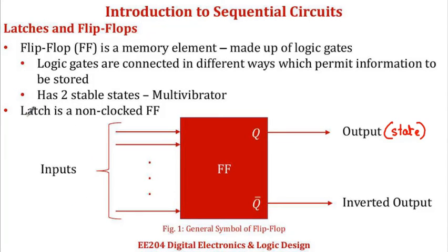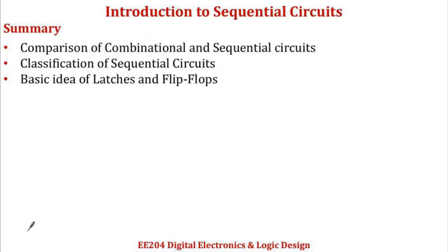Now the term latch is used for certain flip-flops. It refers to non-clock flip-flops because these flip-flops latch on to a 1 or a 0 immediately upon receiving the input pulse, whereas in the case of a flip-flop, you will need a clock signal for the inputs to get affected at the output. To summarize, we have seen the comparison of combinational and sequential circuit.